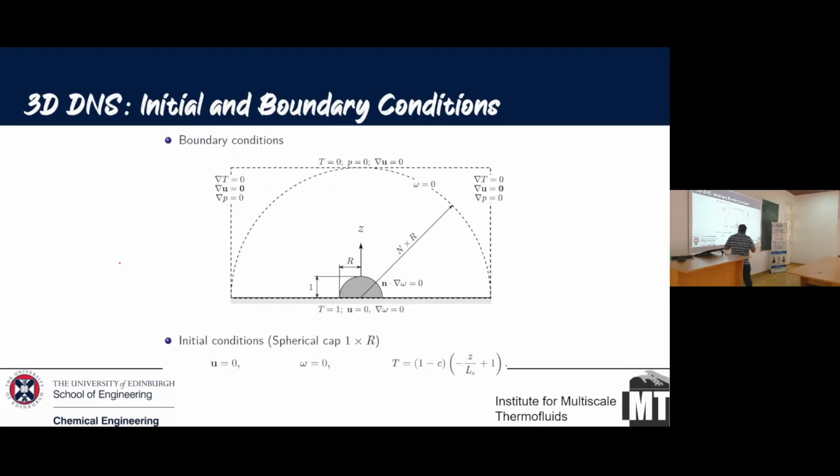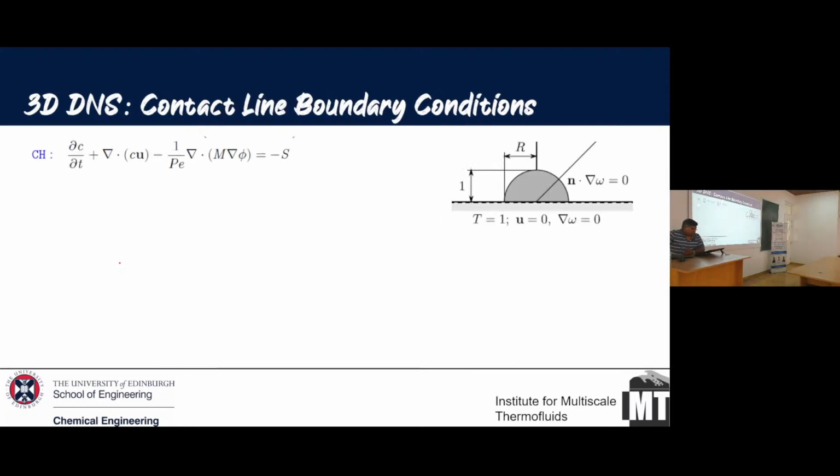And typically, what are your initial conditions? The initial conditions are only that you have a temperature there at the wall. Everywhere else, the velocity is 0. You have an initial cap, and the concentration field in the vapor phase is 0, so omega equal to 0 in the vapor field throughout. Also, given that there is a temperature here, we put a thermal gradient across, so that I don't have to calculate it. It just is there. Okay, so this is what you have.